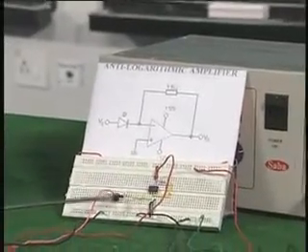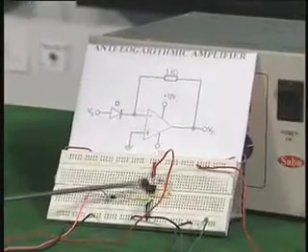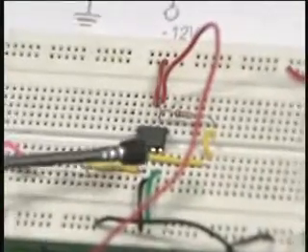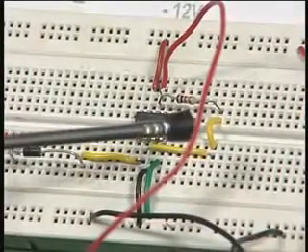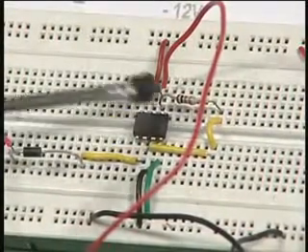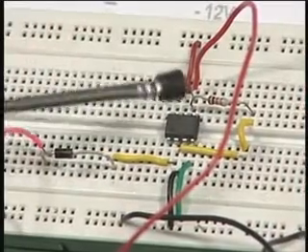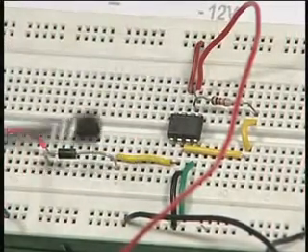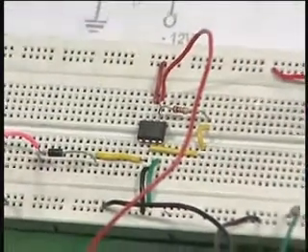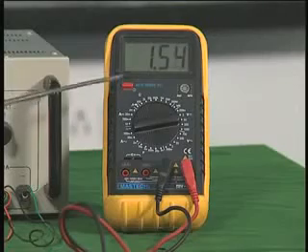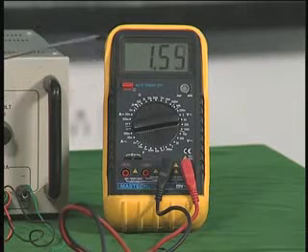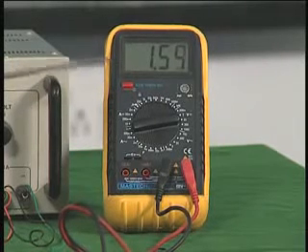You can see the circuit here, the diode is at the input circuit and this is the op amp, and in the feedback I have got the 1K resistor. From the color code you can see brown, black, red, this is 1K resistor. So this is a very simple circuit, and now the output is connected to the pin number 6 to a multimeter. As you can see, the multimeter now reads 1.55 or something volts when I give 100 millivolts. So you get a very large output.